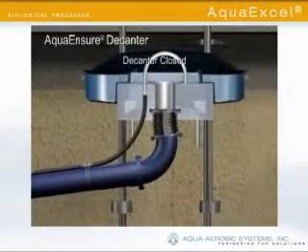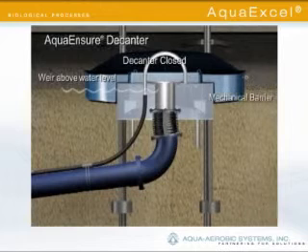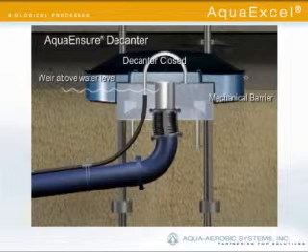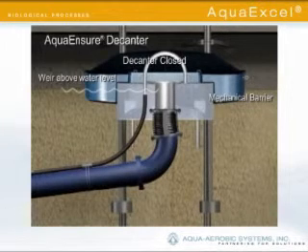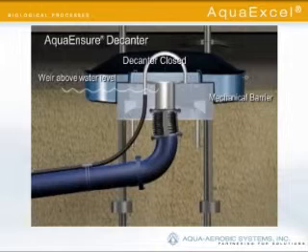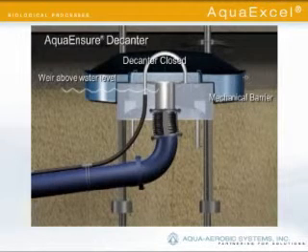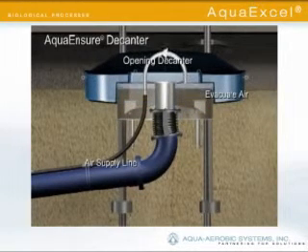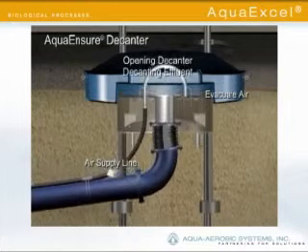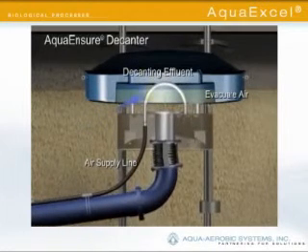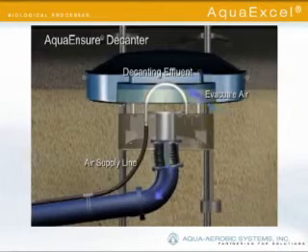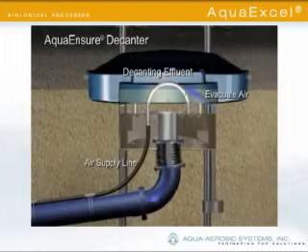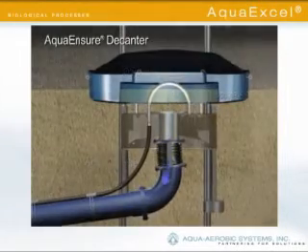In the closed position, the decanter provides added reliability by locating the weir inside the float and above the water surface by use of an air-ballasted chamber that creates a positive buoyant force between the weir and the float. This mechanical barrier prevents solids entry into the unit. To open the decanter, the air from the ballast chamber is released to the atmosphere and water fills the chamber. The resulting loss of buoyancy lowers the weir to the proper decant position, and clear effluent is allowed to exit the system. The subsurface withdrawal and exceptionally low entrance velocities into the weir assure high-quality effluent.